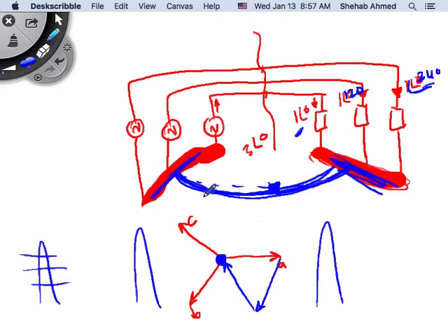So that's why we also add a ground connection at that point. The ground connection is the reference 0 potential. So now, if there is a difference between the neutral point voltage and the ground connection, current will flow in that, and we will measure that and protect against that, right? So the ground protection is actually a physical ground connection. If you go down from the cafeteria downstairs in the Batil, you open the door and go out, there's one small manhole on the floor, and it will say ground rod, right? Look at it, pay attention to this one, it will say ground rod. They have a big metal rod, a big copper rod stuck in the ground, and the chassis of the electrical equipment, the electrical ground connection, is made there.